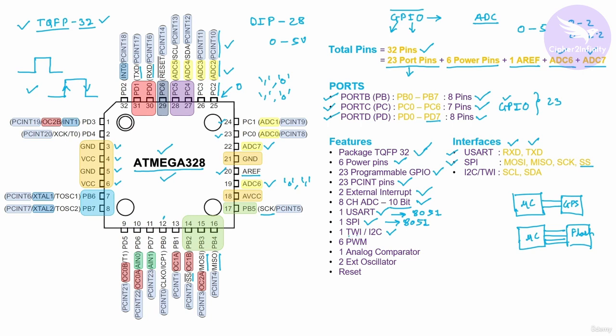There is a big reason why the Atmel controller uses this name and does not call this interface I2C. But from a working point of view, both interfaces are the same. In almost every controller you will find the I2C interface, and only in Atmel's or the Atmega series controllers will you find it called the two-wire interface.